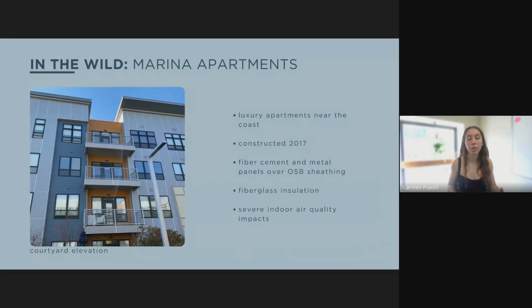And the management wanted to investigate this further because, number one, again, their tenants were getting sick, but also several of their units were unoccupiable, and so they couldn't be making rent on those units. It was just essentially sitting vacant. So this building had flat panel fiber cement siding, or fiber cement cladding pieces, and that cladding was important because it had no water shedding mechanism built into it the way that, say, clapboard cladding might.